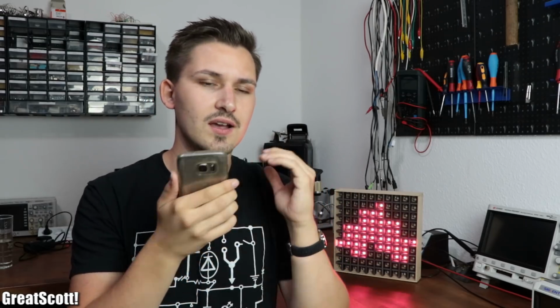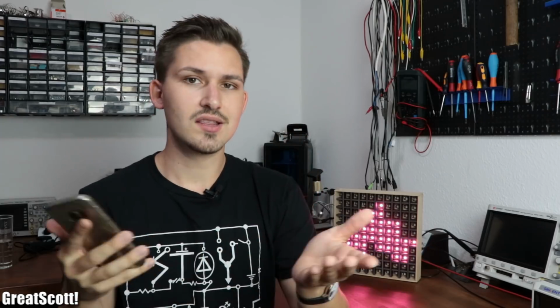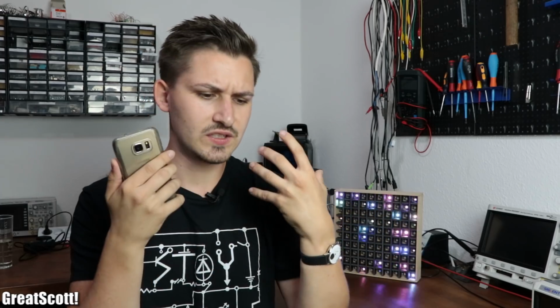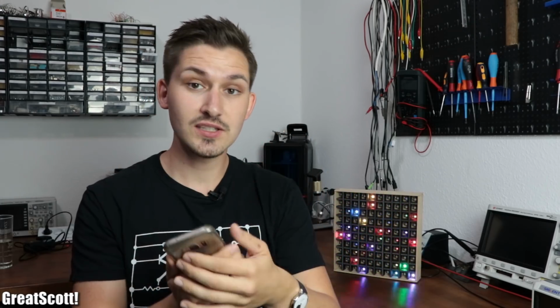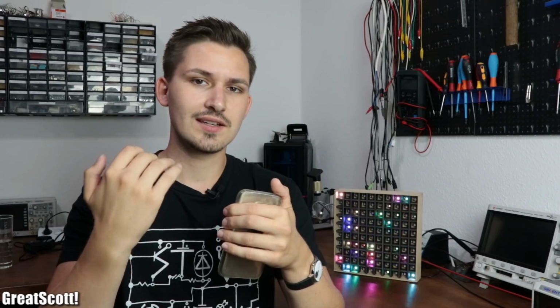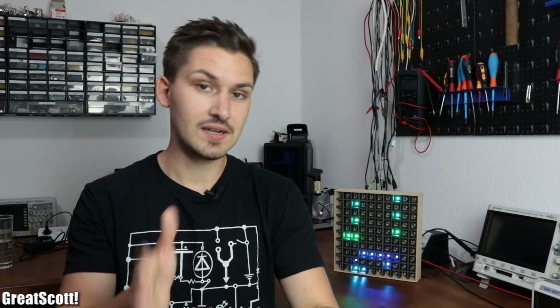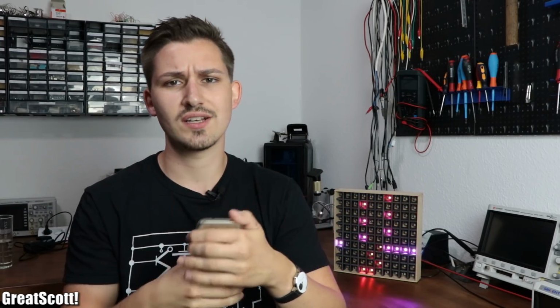And since a standalone buck converter is more efficient than a buck boost, I would go with the buck for the most efficient way. And then again, like I said before, you need a BMS for the short circuit, over discharge, overcharge protection. And then of course, with 4 in series, you would have to see whether the BMS has a balance charge feature built into it, or the safest way, in my opinion, is you just put out a balance connector as well as the XT60 connector, and then you use a suitable balance charger for the job. This way you will always have a perfect balance charge, and you do not have to trust the BMS that is doing its balance job correctly.